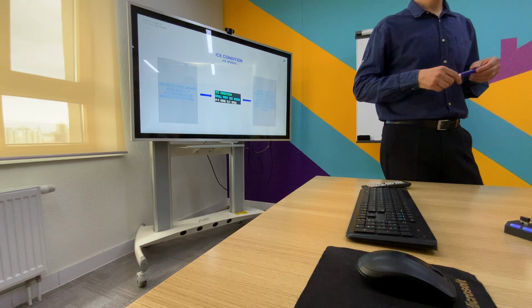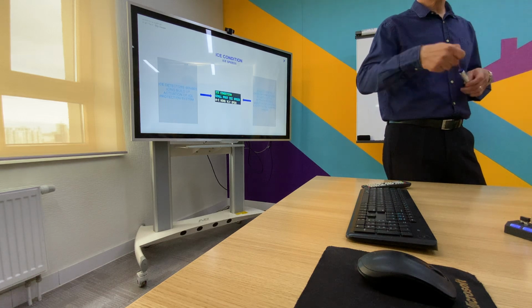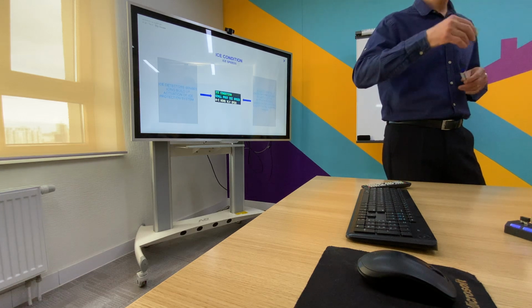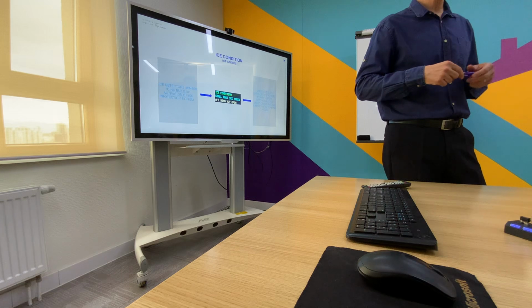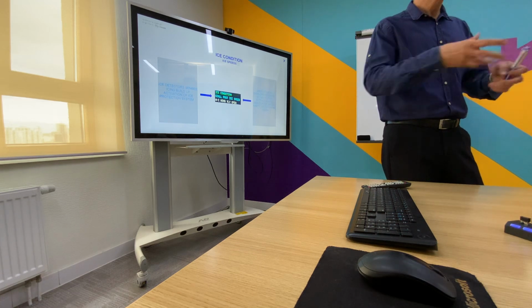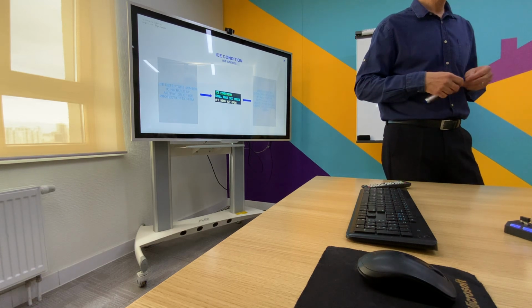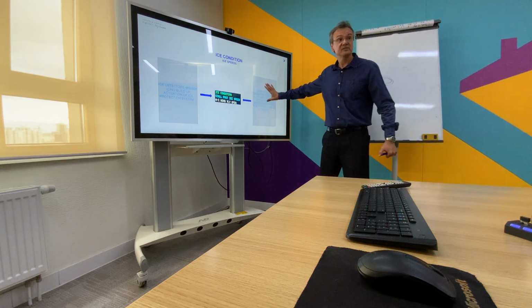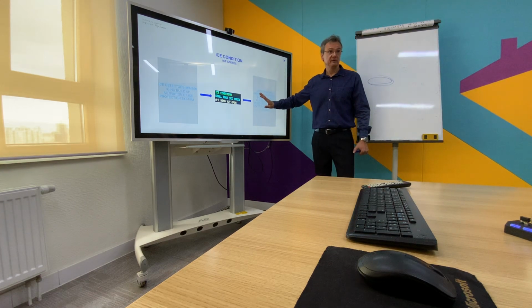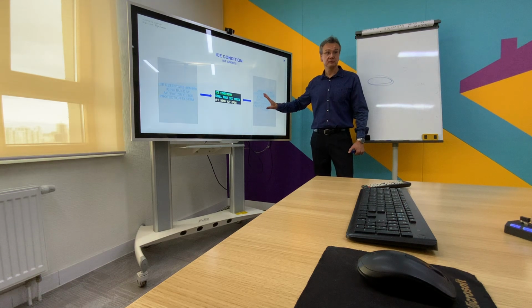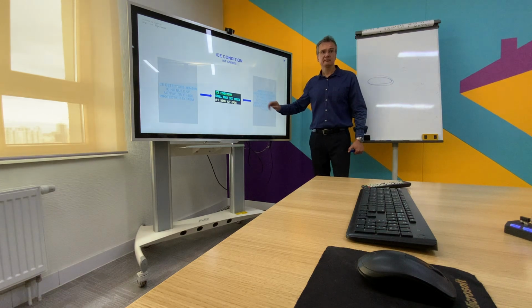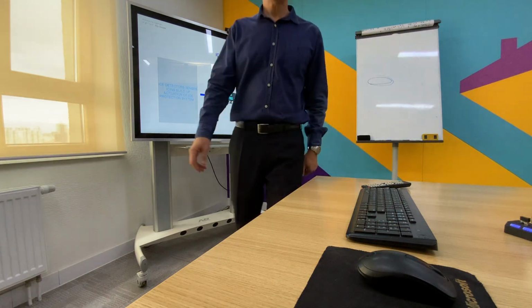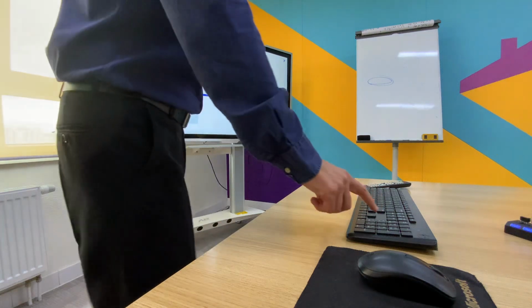It's been happening for a while. Yeah, maybe we have to write it down on the tech log, and ask for the technicians to look into this situation, because it's not normal. If you don't have ice, because on the E1 we don't have this feature, undetected ice speed. We don't have. It was an improvement for the E2. Okay? Yeah. There is no undetected ice envelope for the E1.